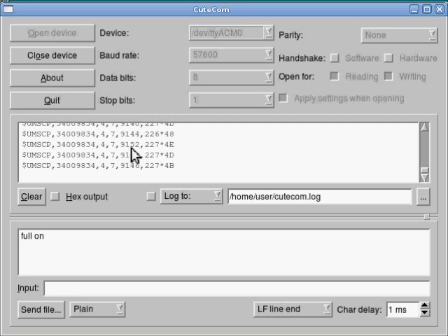So the frequency is in 100 kilohertz units. So to understand this, really very straightforward. This is 914.8 megahertz. These are all within the 900 megahertz United States industrial, scientific, and medical band. You can see that we're receiving signals all over the place. Most of these are around 914 megahertz, and that's just a characteristic of this particular transmitter. We'll pick up data from other parts of the band depending on what type of meters we're listening to. But I do know that this particular type of meter likes to transmit in this range around 914, 915 megahertz.